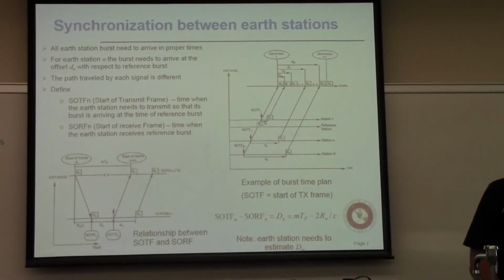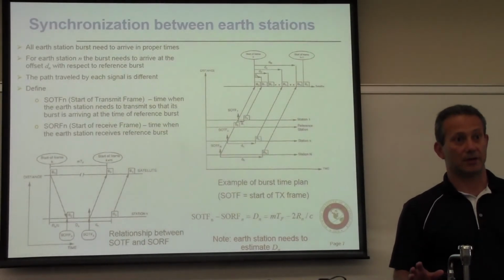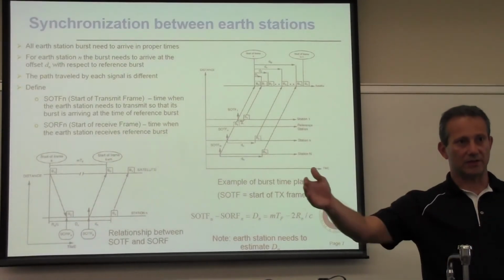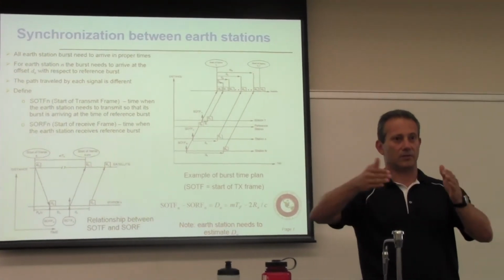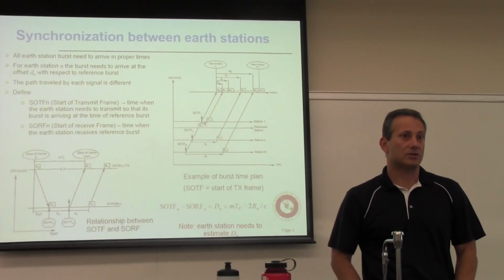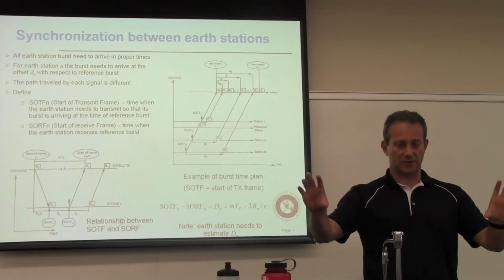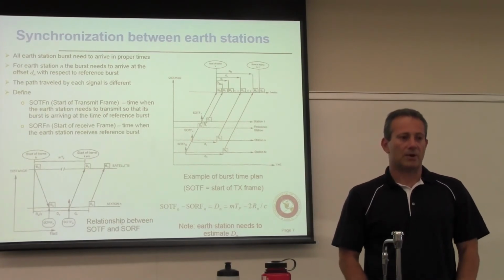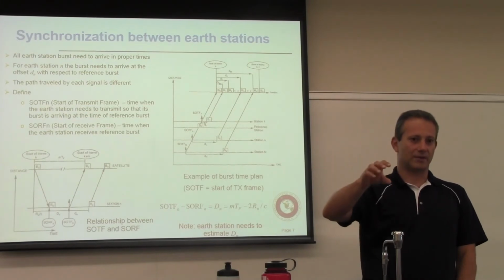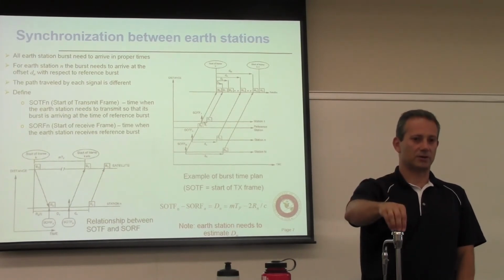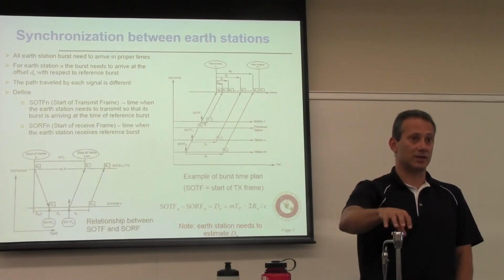Well, remember, the satellite transponder is just a repeater, right? So you're actually receiving everything. You're receiving the signal, so you see right away which time slots have channels or not. So that's one way. You can actually receive the signal and see which ones are occupied. But you would be running a danger if you have in a particular spot a low signal to noise ratio. You may overstep, right? Not realize that's the case.